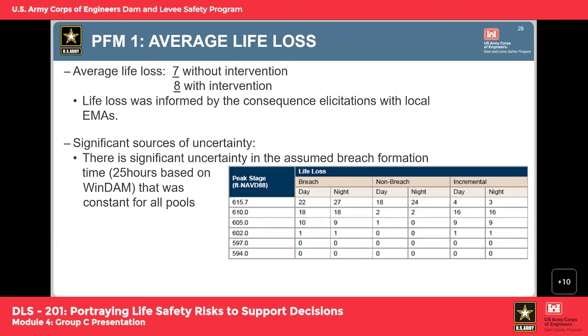So, how do y'all feel about the assumption that breach initiation is going to occur 4 hours after the peak for each flood event? It seems like each flood event is going to bring different amounts of flow. Does that 4 hours across the board seem adequate? I'll chime in. I think it seems a little bit suspect. We could probably run some additional sensitivities to that.